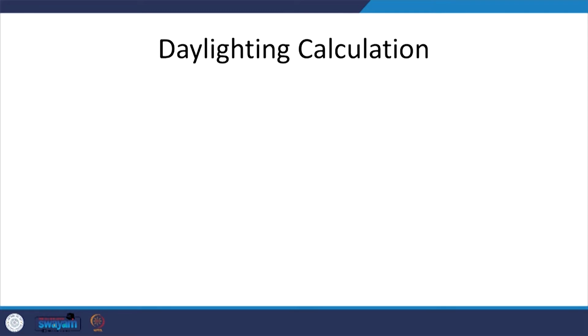For example, LEED requires at least 75% of the habitable area to be daylit, and daylit also has a range of values. In the example from LEED, daylighting is defined using daylight factor; sometimes it is defined using illuminance, or other terminology which we have seen as part of our lecture on daylight. The most commonly used one is the daylight factor.